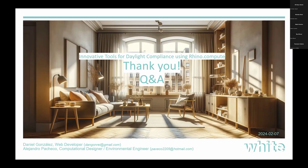So it tries to look for key English and Swedish words, and if it finds the word window or the word fönster in Swedish, it puts it automatically as a window layer, and then it tries to read everything that is in that layer as windows. But if for some reason the name is wrong or it has a name that somehow misleads the system into thinking that it's something else, then you can just go through the list of layers and change it and say, okay, this layer was identified as windows, but it's actually rooms. Then it changes it.